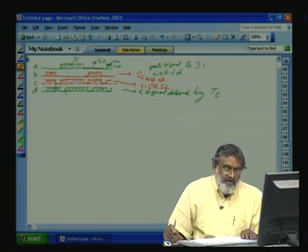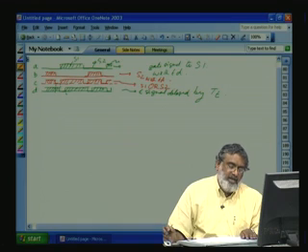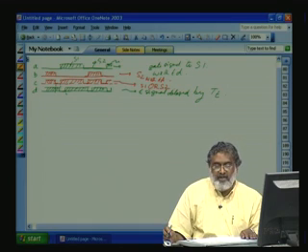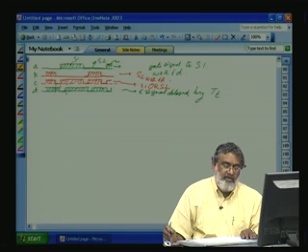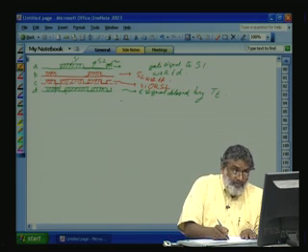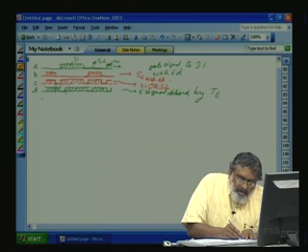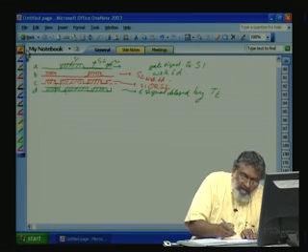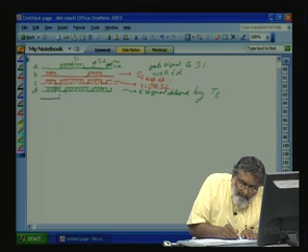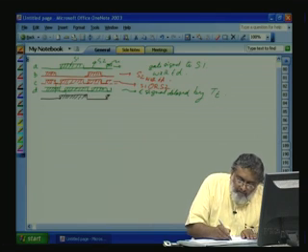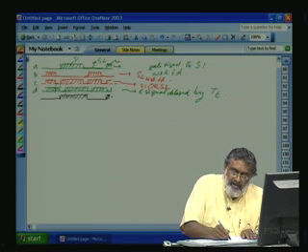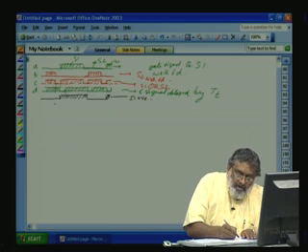Now from this one, we will generate the actual signals for S1 gate pulse and S2 gate pulse according to whether the current is positive or negative. So let us say S1 positive is the signal when the current is positive. So I will turn on the device here, the actual signal I will generate here. This is S1 positive. Now what about S2?